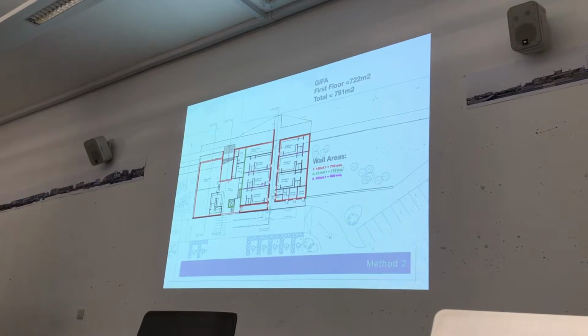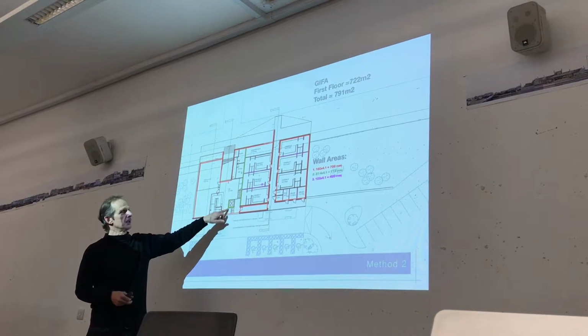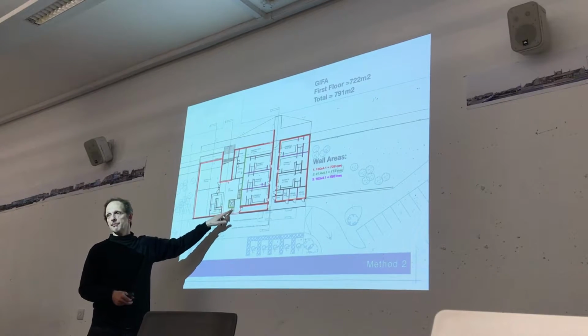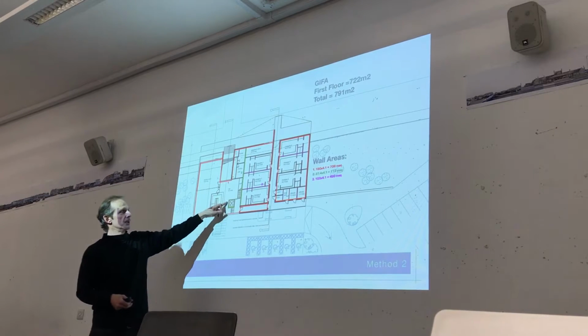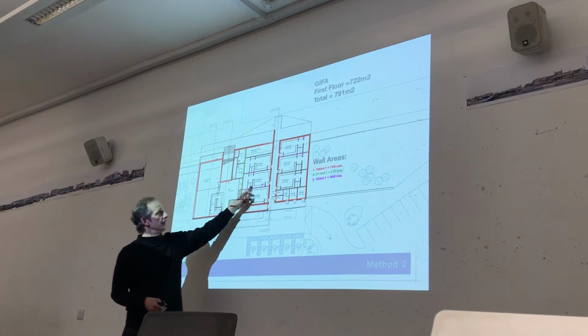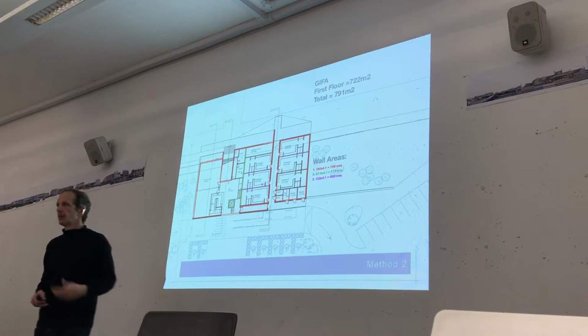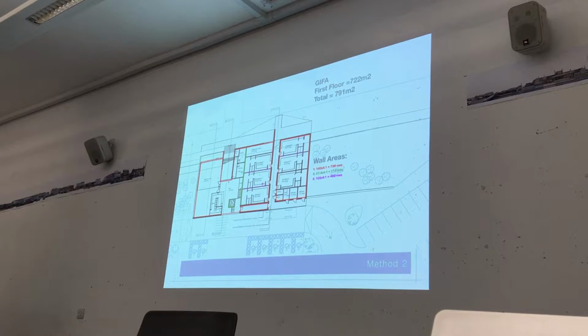And the same, then you start to, where you've got different specifications, different construction methods, the lift shaft might be reinforced concrete, so the green bits might be one material, the red might be another material, these internal walls might be something else. So you've got 3 different elements, so those will have different costs against them related to the area of that element. Yeah.